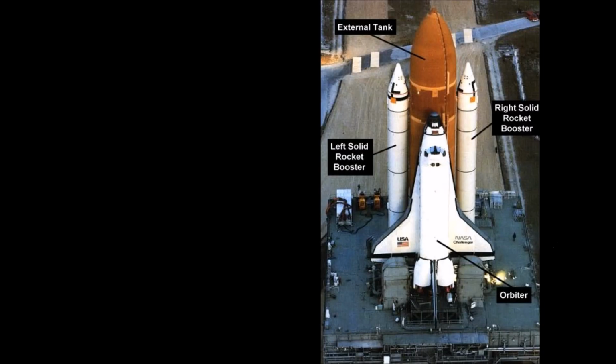Take the situation of the Space Shuttle Challenger. A very similar situation occurred here, where these solid rocket boosters are assembled in segments with these black O-rings separating each segment. It was found that leaving the shuttle overnight in some rather low extreme temperatures resulted in the fracture of one of these O-rings. This caused heat and flame to shoot out of one of these connectors, and actually be applied to the outside of the external tank.